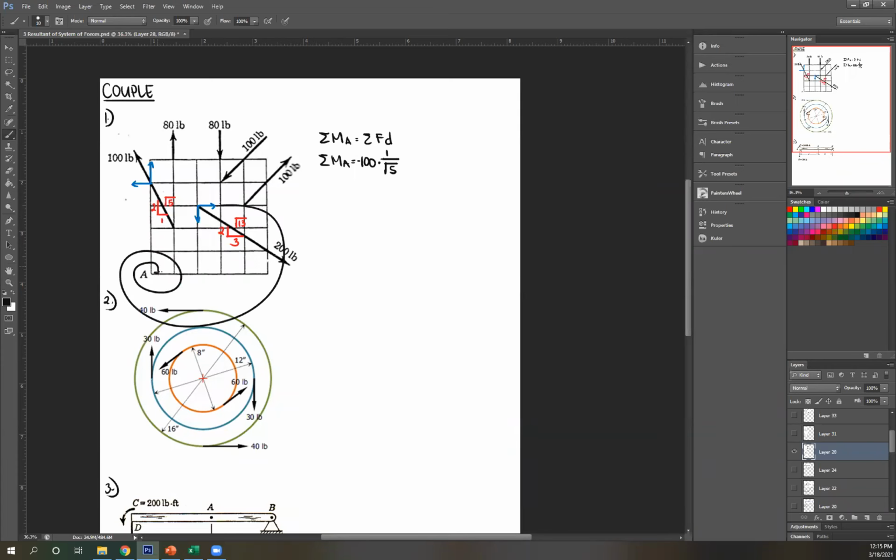Rotate it about A. Once again, that's counterclockwise, so negative, copying your force 200. This is horizontal, so the side that is horizontal, that's 3 over square root of 5 multiplied by distance. Oh, I forgot to multiply by distance here. So this is only the horizontal component multiplied by distance. We're taking it about point A, so this is the perpendicular distance, 1, 2, 3, 4.